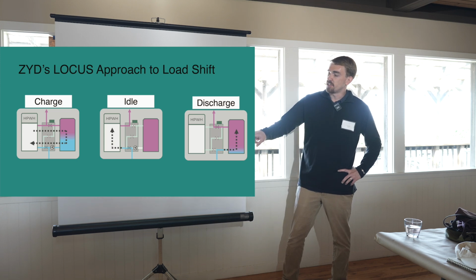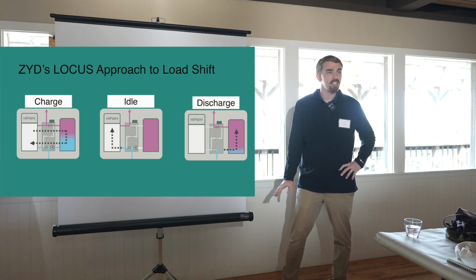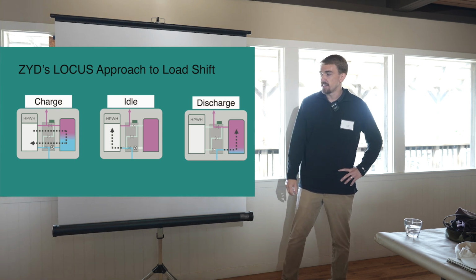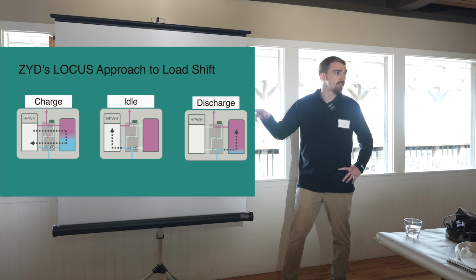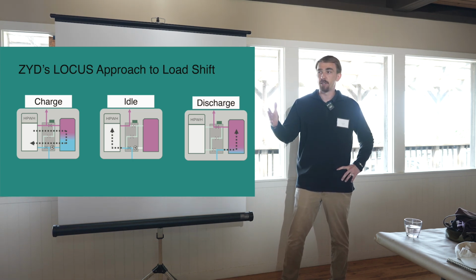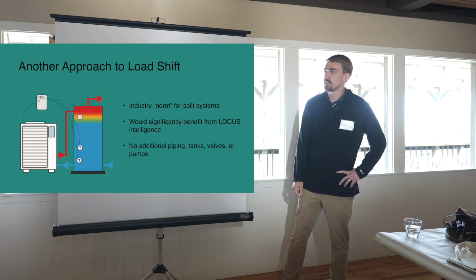And then finally, during the shed period, we are discharging this storage, and we're isolating the heat pump. So the heat pump doesn't see any draw; it can just sit there happy and asleep, and this extra storage will draw down. And they're going to size this storage to be able to cruise right through that shed period without turning the heat pump on. And next slide, please.